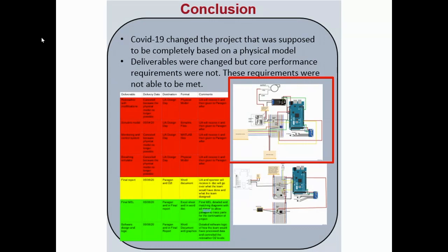The first wiring diagram demonstrates how to properly integrate all of the necessary sensors, microcontroller, and electronic components to allow for operation of the blower for the breathing simulator, as well as control of nitrogen addition into the system. As is annotated in this particular wiring diagram, Paragon will need to implement a 10 to 35 volt external power supply in order to meet the demands of the operating voltage of both the differential pressure sensor as well as the blower.